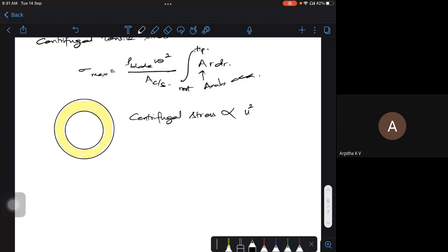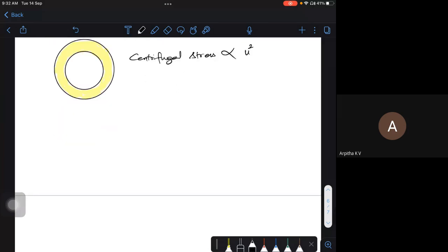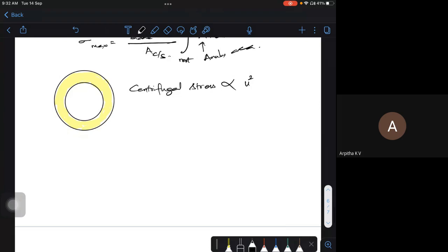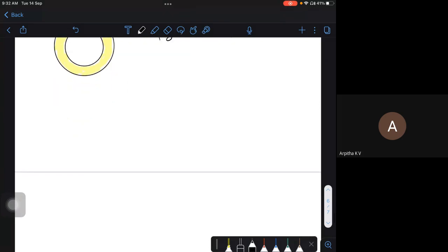Okay. To be maybe more practical, what will happen? Let me tell you. In practice, when I try to design a centrifugal compressor or an axial flow compressor, they take a particular blade sectional area and reduce it. This is my experience from when I was in the compressor team at GE. The blade sectional area is slightly decreased with the radius to relieve the blade root stress.